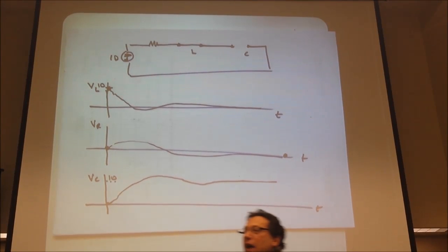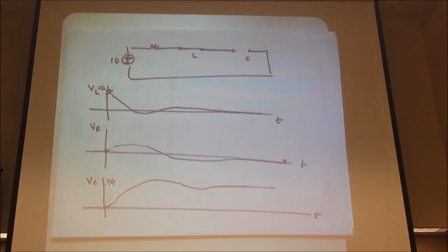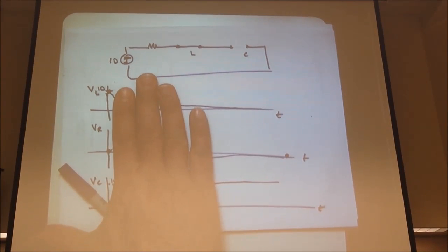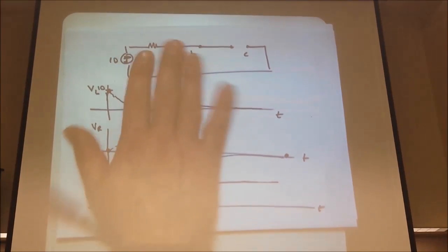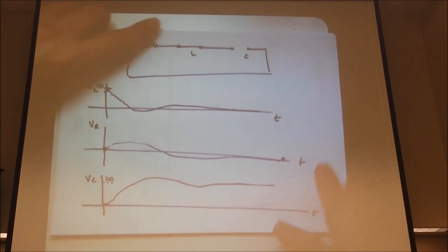We certainly have a non-zero value for the voltage at some point because current starts flowing as the capacitor charges up. But eventually it goes back to 0. And we'll see expressions that look something like this. So these are initial states with possible curves associated with voltages as a function of time. What's really important here is to look at the initial conditions and then look at the final conditions for this DC step function source type of problem.